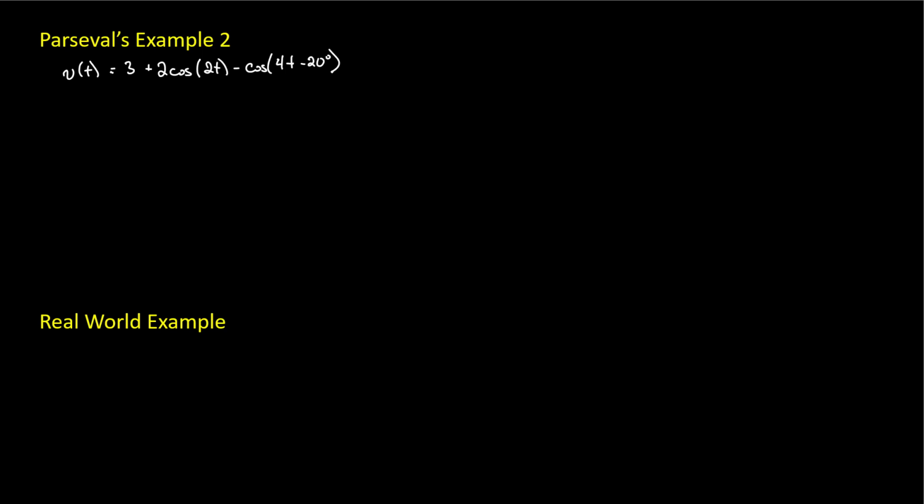I could have just as well given you a square wave or a triangle wave or some other wave, and you do the Fourier series breakdown for a certain number of harmonics to get it into a format that looks like this. Now the question is, given this waveform, I want you to find its RMS voltage. Remember, that's the DC equivalent, so that if you put that DC RMS value as a voltage into a light bulb, it would light just as brightly as this complicated changing thing.